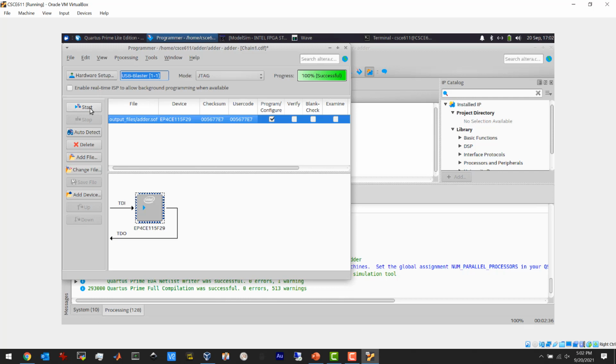Yeah, so that's basically it. Now notice that this hasn't changed because I didn't actually connect any of the pins that go to this LCD display. You can do that if you want. Likewise, I didn't connect to Ethernet or VGA or the audio chipset or the USB. Also, be careful when you program your board, make sure you plug into the leftmost connector up there. That's the USB blaster.